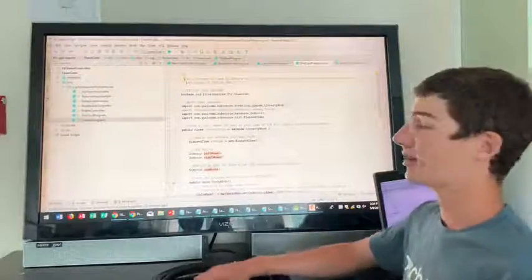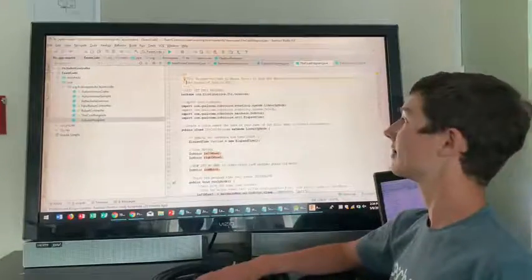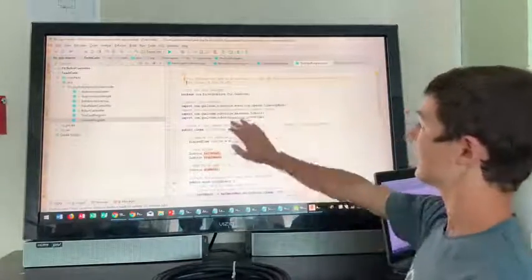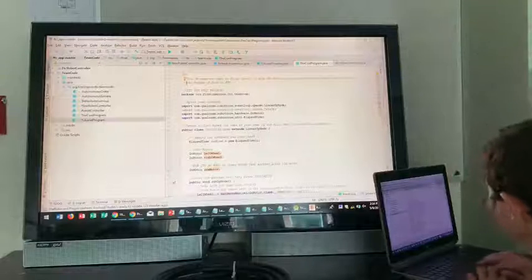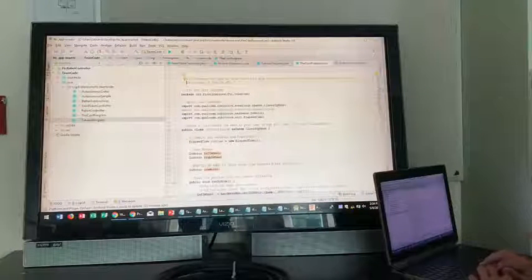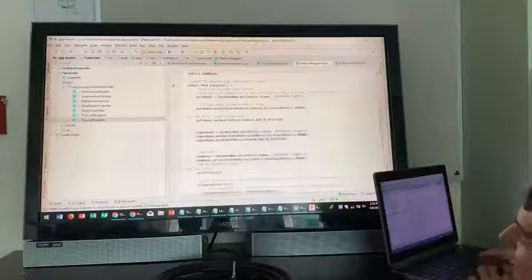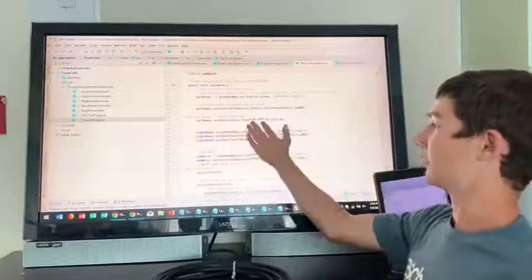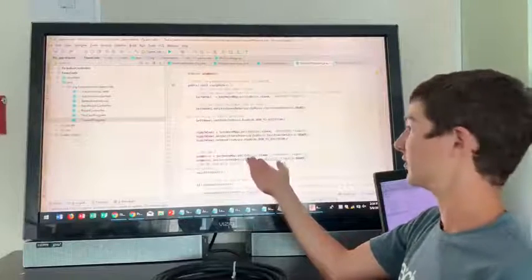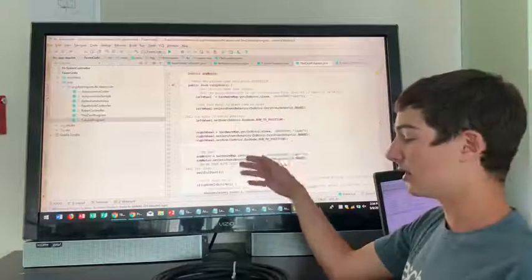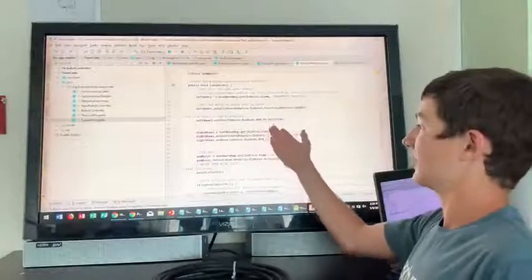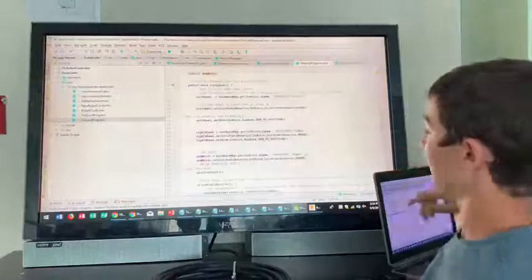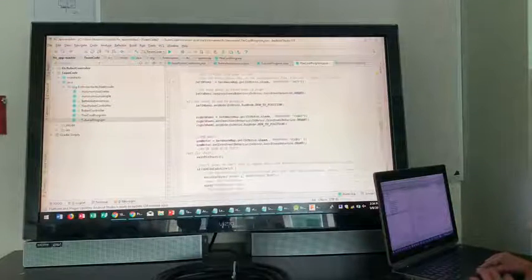I'm going to be explaining about encoders today, and so I'm going to set this program up just like we have in past programs, and we're going to just scroll past all of this. Super simple setup, and everything is exactly the same except we're going to set this set mode, which is going to set whether or not we're tracking the encoders, or if we're running without the encoders, or if it's going to be like running to a certain position. And we're going to do that for just these wheels here. And this is our two-wheeled robot here.